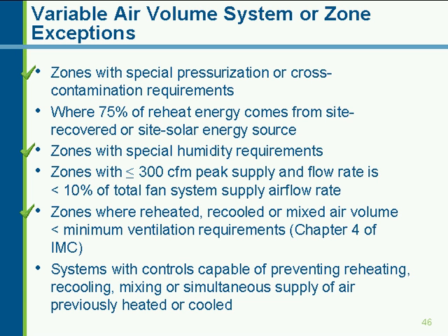But my general interpretation, or where I've seen this used, is places like museums, archives, places where archives are stored, possibly some areas of hospitals or laboratories where they need special humidity ranges to be kept in place. I think if you can make the case that you need to keep your humidity in the zone within a narrow band, that this exception would come into play. But those are the types of applications where I generally see this exception being used.